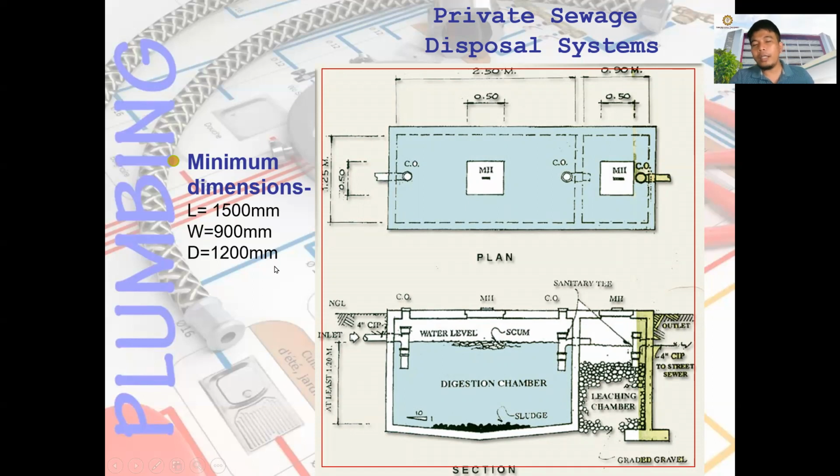But now, in the National Plumbing Code provision for septic tanks, it should be of 3 chambers. Two chambers are now prohibited for usage. But in some cases there are also exemptions. If you have a smaller building and a smaller area, you can just use a 2-chamber septic tank.